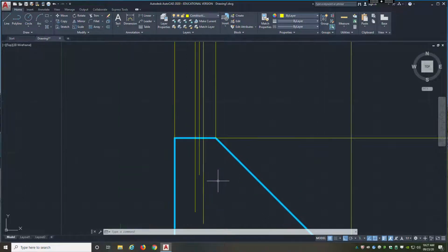All right, now that we have the proper location for our hole, I'm going to take the hidden line type and line tool and start at this particular intersection. We'll do that. And we saw last time that it goes down 3/4 of an inch, so 0.750. And I'm going to shoot it over to perpendicular snap and bring it up. That's all I need there.